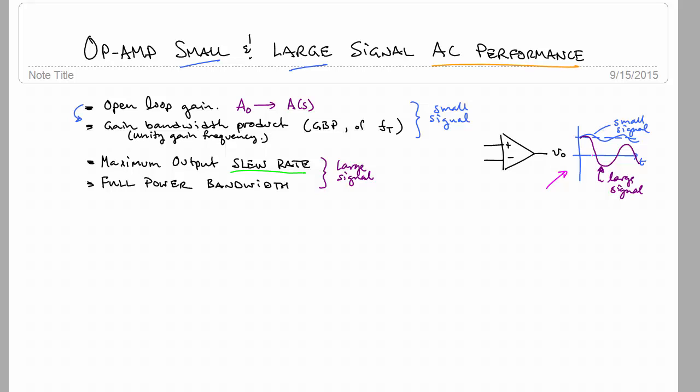In blue, you see the example of a small signal. So just a reminder, small signal is where the deviations or the changes in the output or the signal are just small deviations from an operating point signal. So the amplitude of the time-varying portion of the signal is very small relative to the DC component of the signal, which is what you see with this signal here.